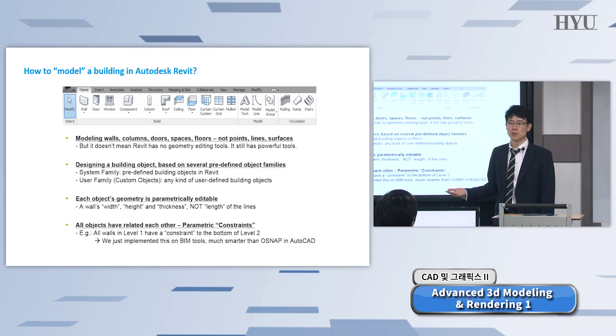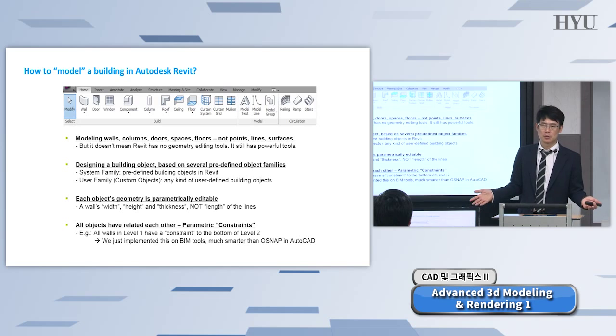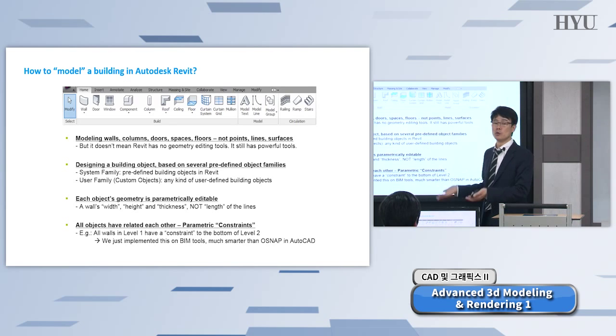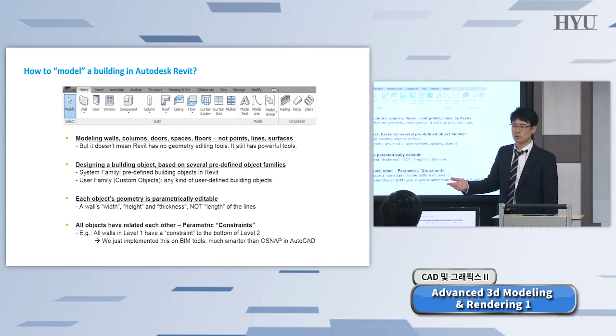Window object also mandatorily requires walls, okay? And actually they're supposed to be opening, and then that opening going to be filled with doors or windows. That's fundamental architectural mechanism. This application explicitly knows that. So your design could be very realistic, okay?